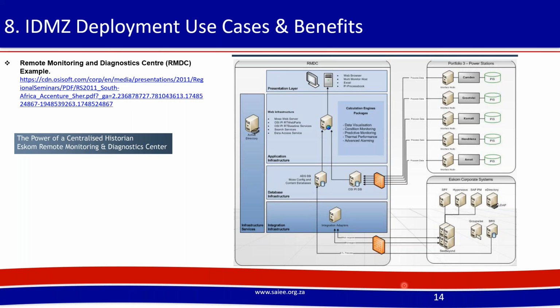Each power station will have a DCS, and then from that DCS you will have a historian network that interfaces with that DCS. Because that historian network and the DCS belongs to one person, typically just putting a firewall in between is sufficient, because it's the same network, it's trusted both ways. It's just that the other one is more diagnostic.